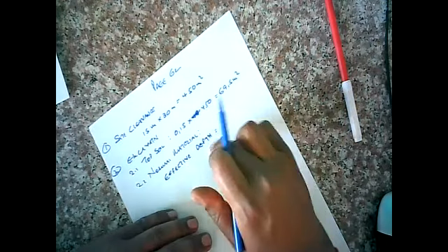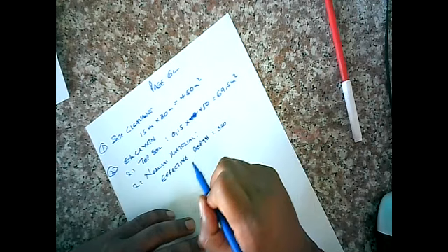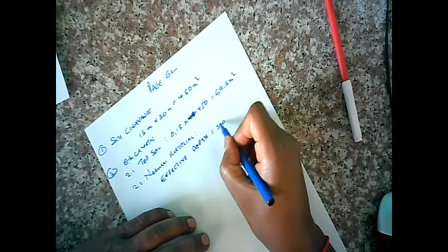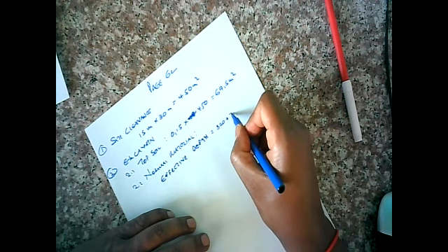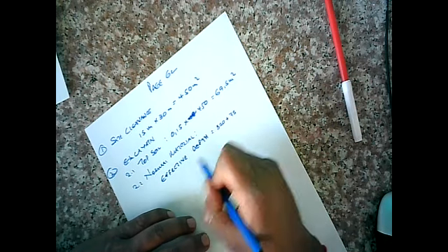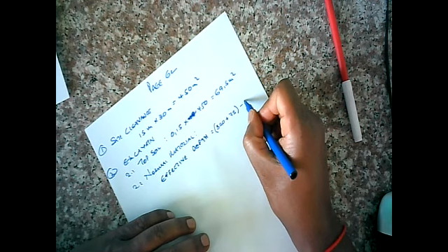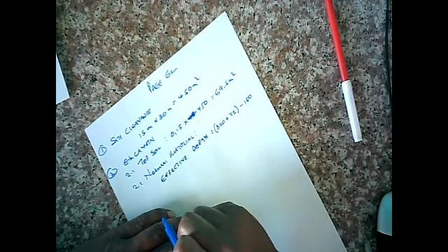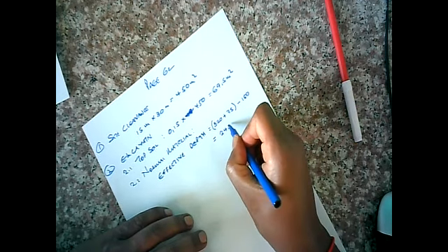Now what's this effective depth? We're going 320 millimeters below the ground level, all right? But we also have to accommodate for the blinding layer, all right? But in the process, we still need to take off the topsoil, 150 mils. What is our effective depth? 245.